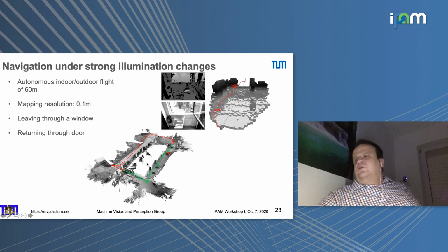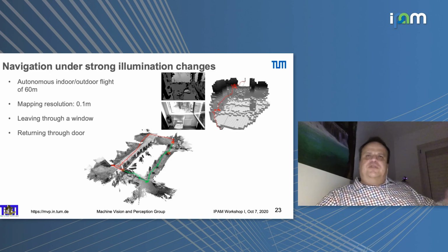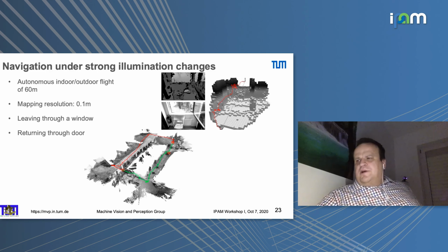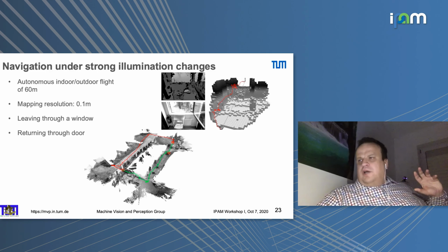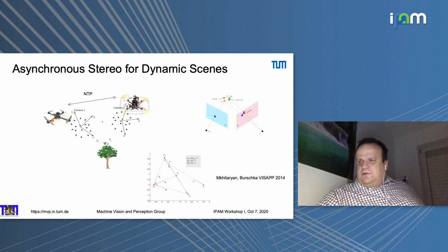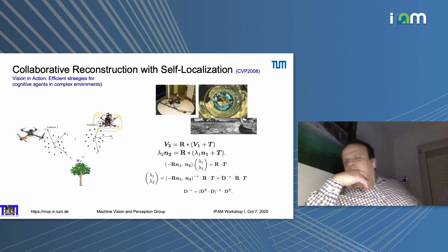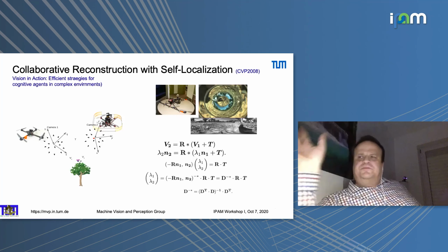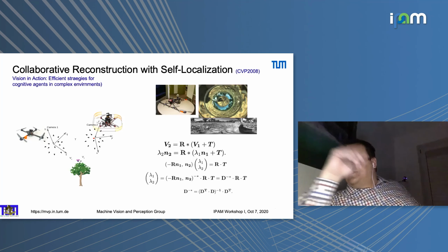The only way how you could do it, stabilizing the drone basically with a visual system, was A, to rely on IMU and compensate just the drift, and B, have a system which is providing correct fusion so that the system will not diverge in these 3 to 4 seconds while the camera is switching from dark to bright and bright to dark. Oops, here's my 2 slides. So this allows us, of course, now to build systems which, well, this is something we see a lot now.